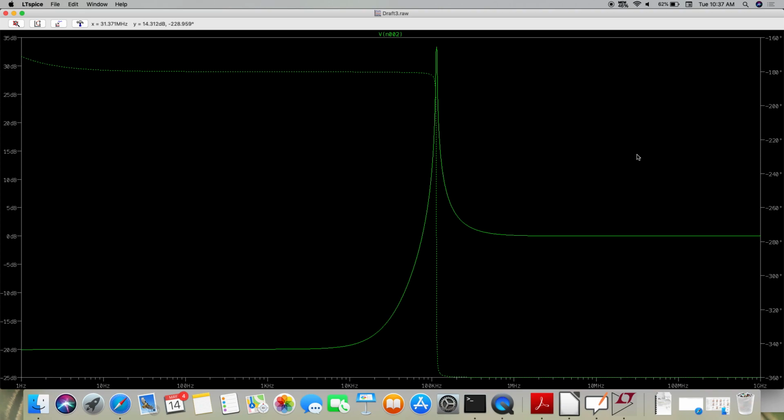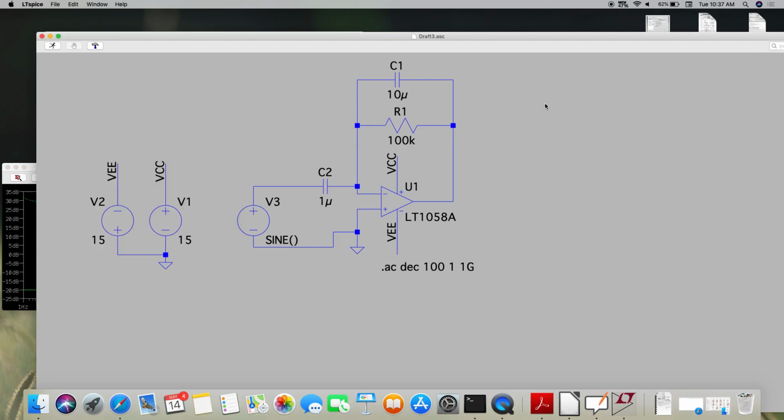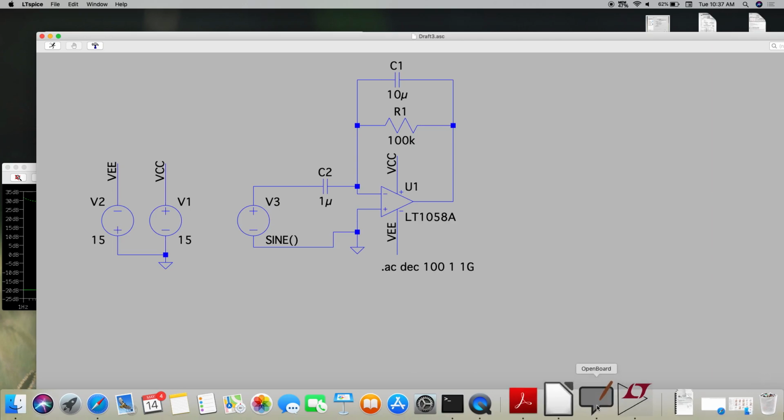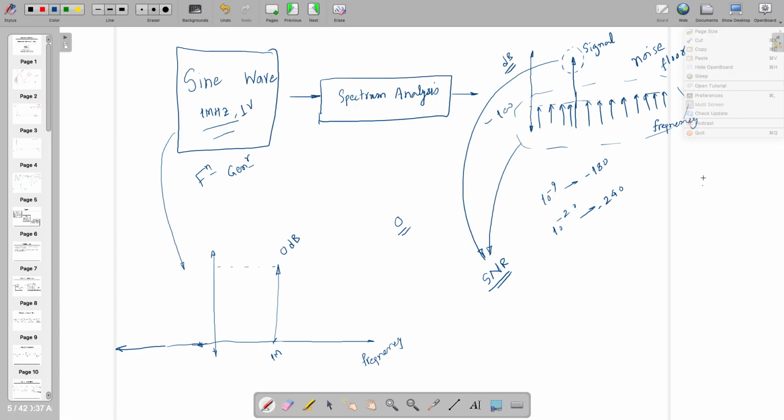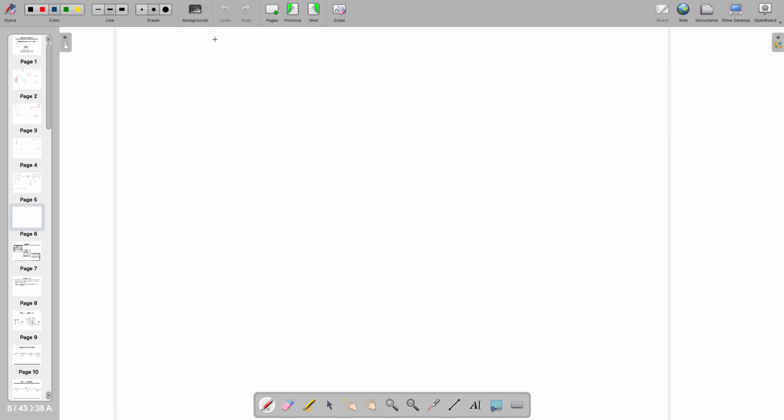You can look at the transfer function and observe how the phase and magnitude are behaving. But the most important part, as I told you, is that the simulator is not simulating this circuit, but something called a netlist. A netlist is very easy. The netlist is what tells you how these components are connected. Remember, all these components are defined in the library, right?